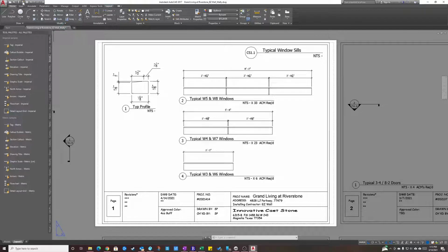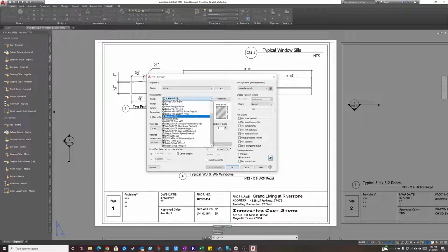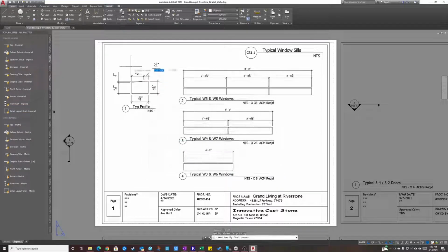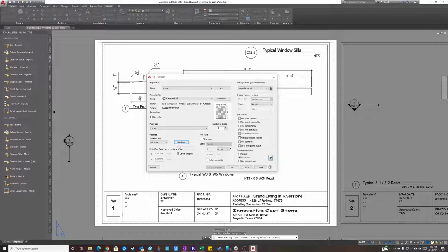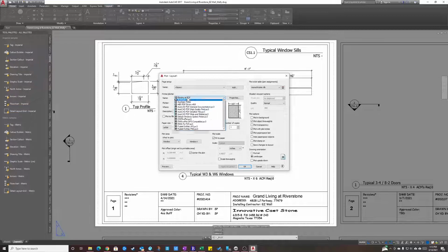You're going to click on, obviously, save. You're going to click on print. You're going to print this to a PDF, and the rest is history, man. I mean, Bluebeam PDF. I apologize. Let me go back. So you're going to click on print. Make sure the PDF printer is selected. Monochrome is always ideal.